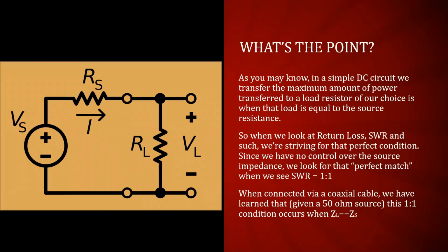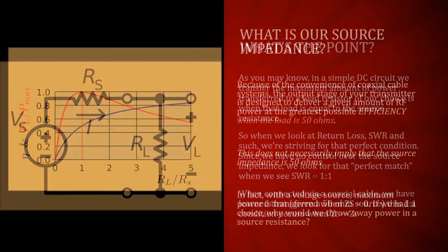I'm an amplifier designer, and what I did was tune my amplifiers for maximum efficiency. That is power output divided by power input, maximum efficiency, current, voltage, and so forth. And I didn't care about VSWR. I only cared about the return loss that is there.